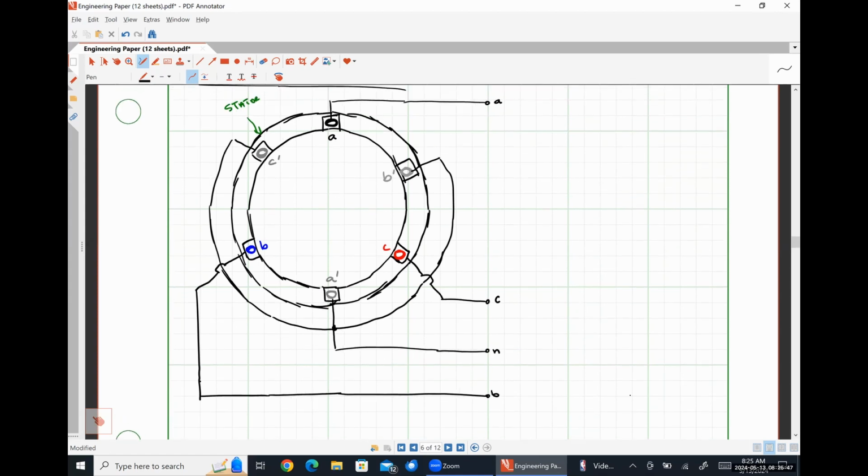So right now, effectively what I have is 3 different inductors, because we just have coils of wire kind of tied together. And then we have access to their point of interconnection, which is our neutral terminal, as well as the other leg of each inductor, which we're calling our A, B, and C phase connections there. Okay. So this is how our stator is set up. Okay. This is commonly referred to as a Y-connected machine. And now we're going to talk about our rotor.